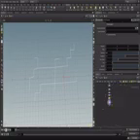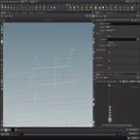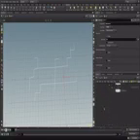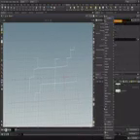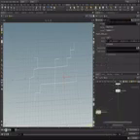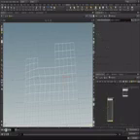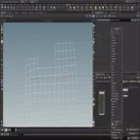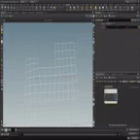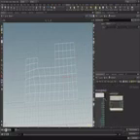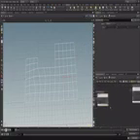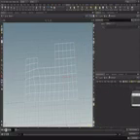So after this convert line, we're gonna drag this stuff down a little bit, and I will be placing down a primitive up. And inside of this primitive up, I will be getting the position. I will place down a vector to float, wire that into the position, and now I'm going to use the x value to create a sort of ID attribute.